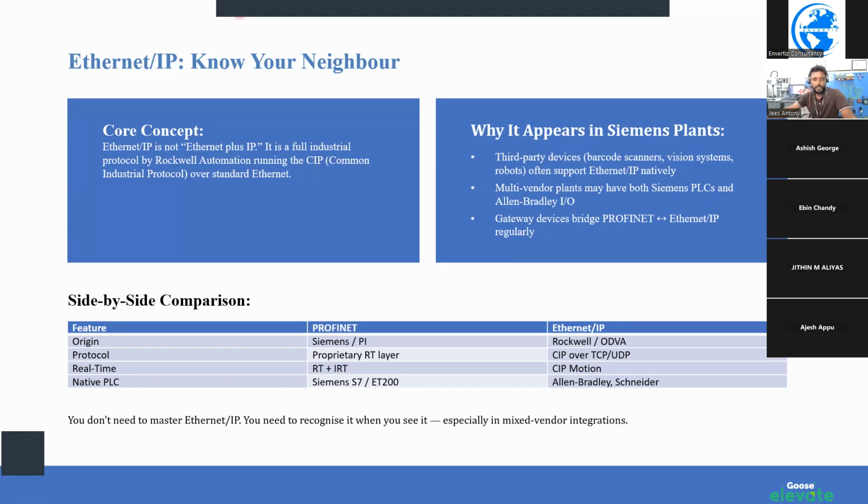That kind of difference you can see between Ethernet IP and Profinet, because Siemens is focusing on much faster communication. That is why we can see better latency in Profinet. Ethernet IP is closer to common Ethernet devices, so data exchange between Ethernet IP devices and other devices would be very easy.